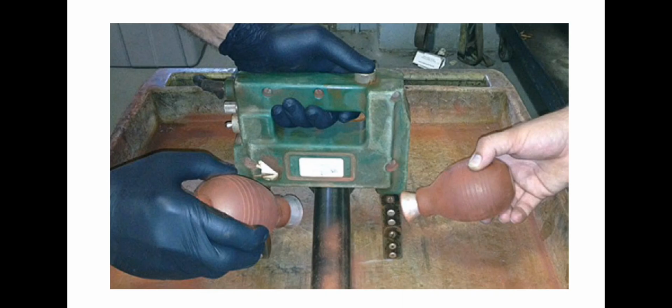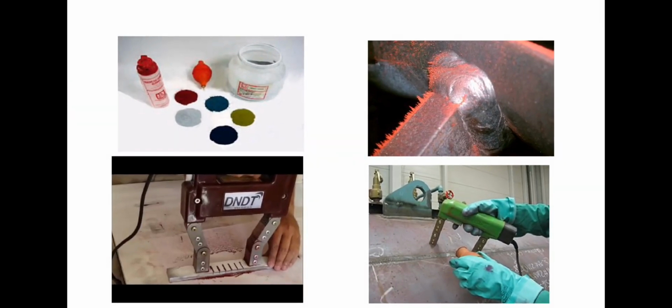This is an example of magnetic particle inspection using a yoke. This device is known as a yoke. The yoke will provide the magnetism, and we use blowers to blow away the unwanted magnetic particles. These are other examples. We use magnetic powders in different colors for different occasions, and we will get results like this. This is the yoke. The yoke is used for making the material magnetic.